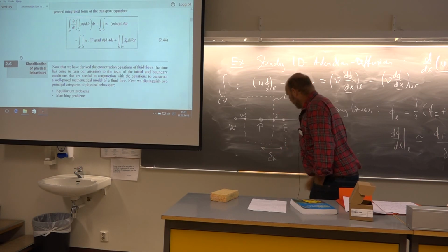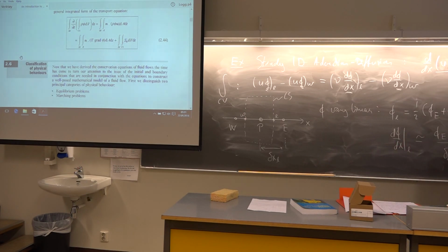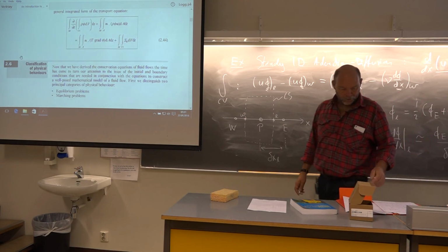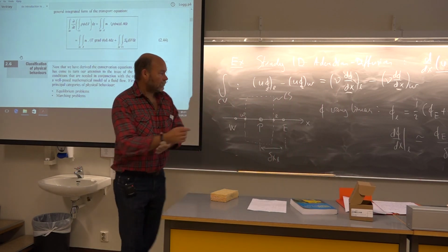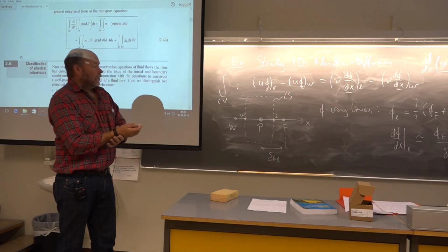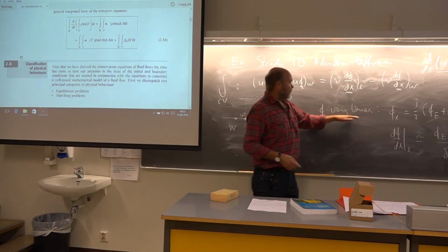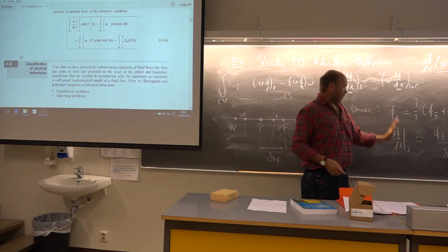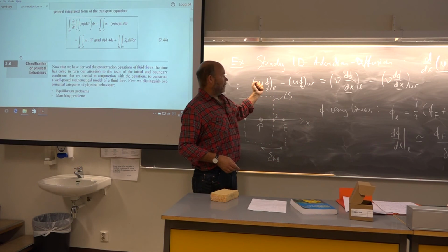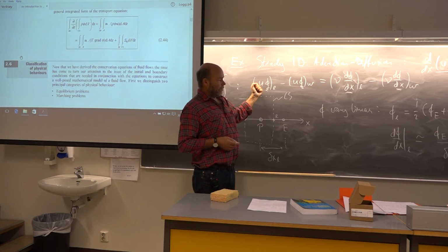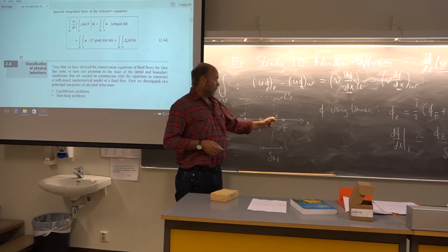Actually, these delta x's may change from place to place, so in general, yes, we need an index for it. So you see, the linear variation helps us formulate whatever we need to obtain our algebraic equations, given the phis at certain points.